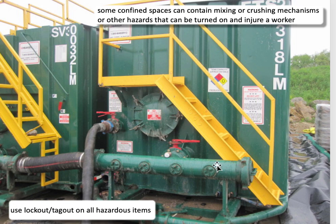So here again is an example of a confined space, and it also highlights the importance of proper lockout tagout. So you'd have to lock and tag out all of these areas before you make your entry into the confined space. And you can see the DOT placard on the side of the blasting booth.